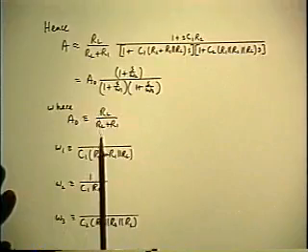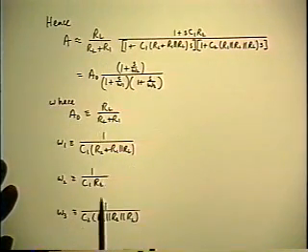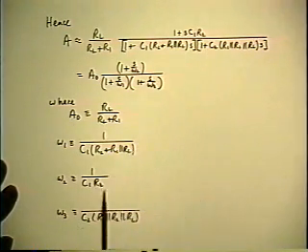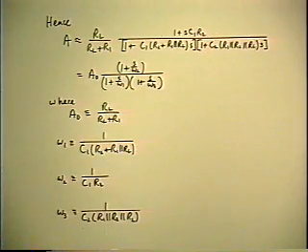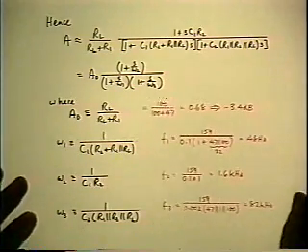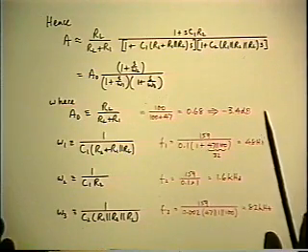Here's simply a listing of the zero frequency gain and the three corner frequencies. The zero is already explicit, and these are the two simple ones that come out from the quadratic solution as the assembled numerical values also.